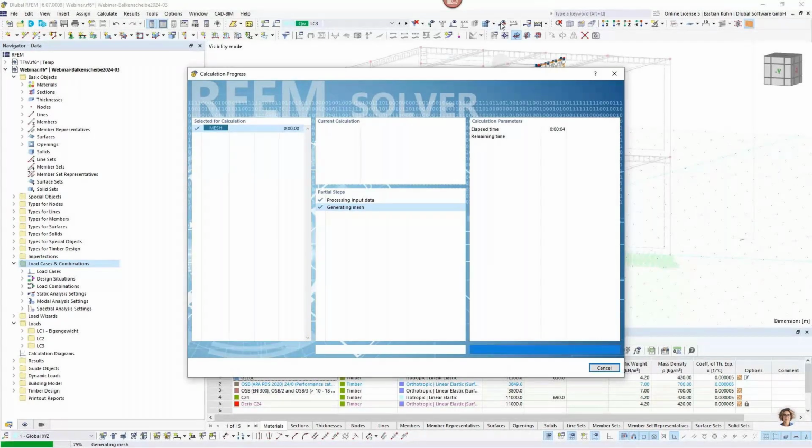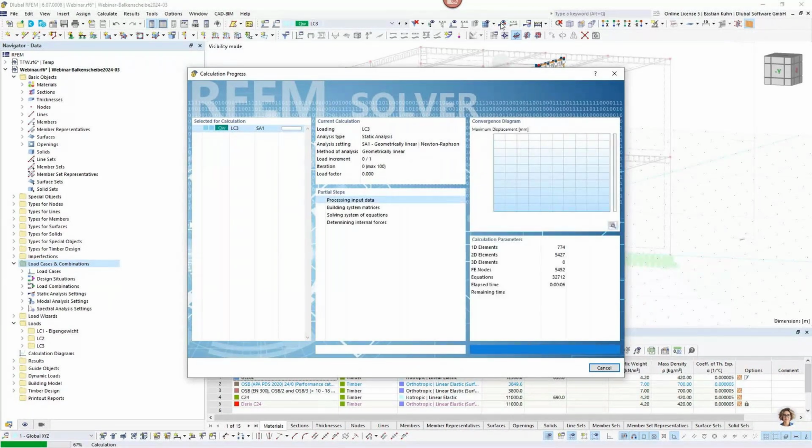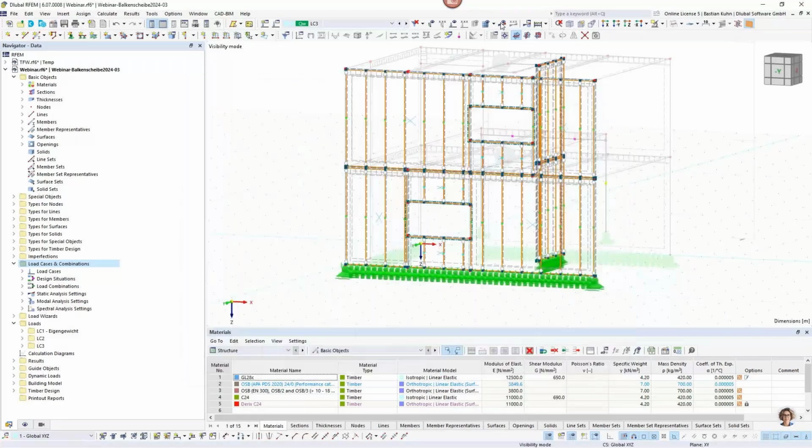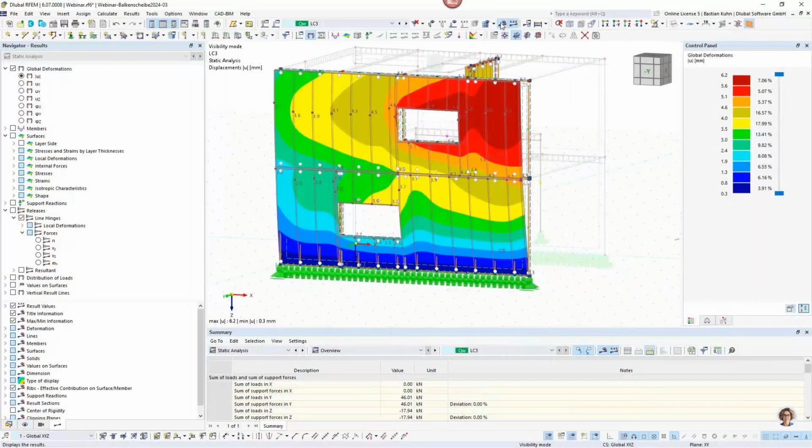Okay, it's not a real small structure, not even a big structure, but yeah. I also use the building model inside just to get my masses all around. So masses maybe also a good point. One other advantage of using such a 3D object is that you can use the stiffness of the timber frame wall similar as CLT for every calculation. So also for your dynamic analysis, you can create response vectors and use it for this.